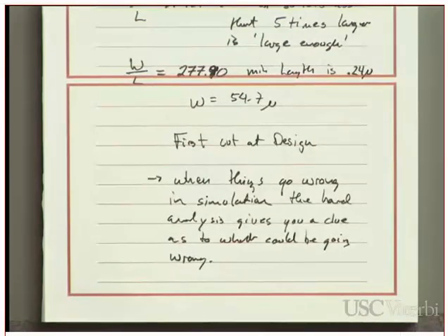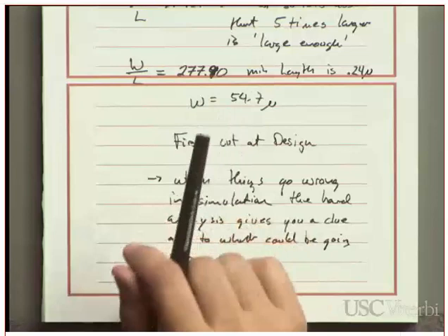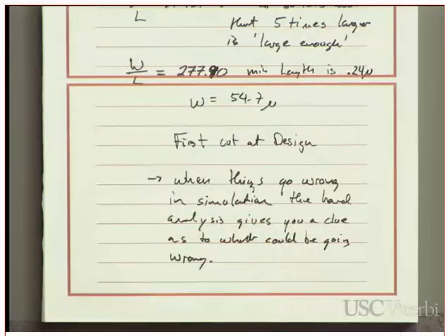Okay. And then on top of that, you may have to design a matching circuit between two things, which is much simpler than this, but for that kind of stuff, you also have to take into account the frequency response of that matching circuit. So if you need a wideband match, you have to make sure that you have a wideband match. But in the past, we've only been looking at about 100 megahertz on a system that's running at about 2.4 gigahertz. So the bandwidth of the matches doesn't have to be that broad for most of these circuits. Other questions?